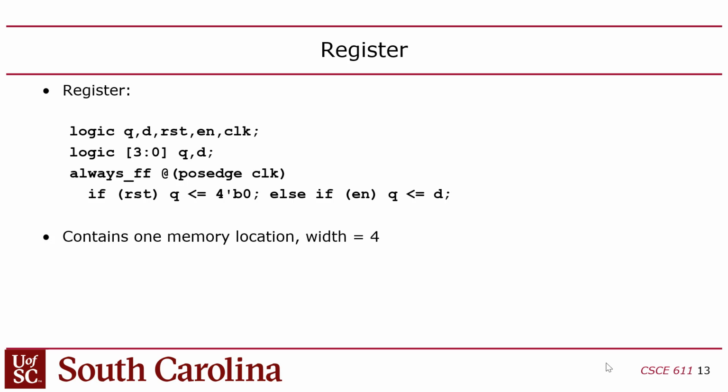And this will be a don't care because you can't read from the 7-segment displays and put them into a general purpose register, right? So you're going to use the RS register, like for example, 5, in which case you're going to take the contents of register 5 in the register file and send them to the hex displays by enabling this register that I'm talking about, this GPIO register, okay?